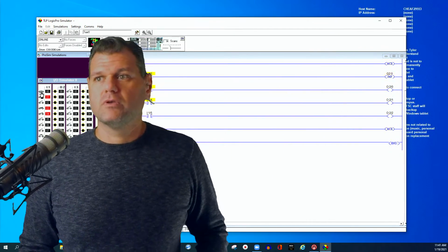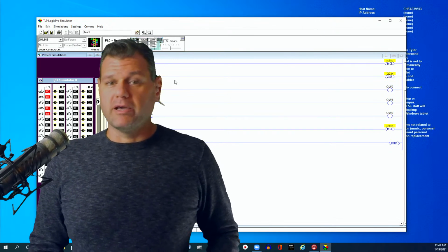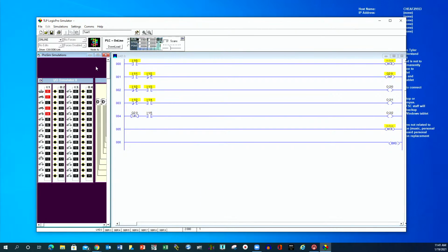Okay, but something that is happening is that my rung 1 is jumping over all these logics. As you see, this is active, and these are true. So normally you'd have a true state, but for that reason, it's not doing it. So let me turn this off. Let me switch that. Okay. Now the jump has gone away, and see what happened? These all came on. So let me do it one more time. I'm going to hold it down.